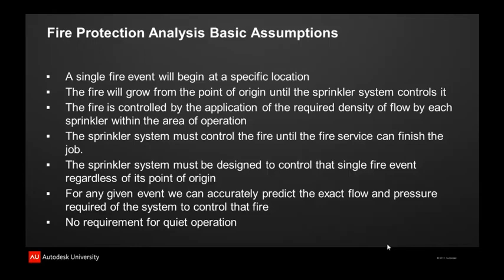Next, the sprinkler system must control the fire until the fire service can finish the job. So it doesn't have to operate all day long every day. It's just when there's a fire, and only until the fire department shows up and actually puts the fire out. This is pretty key, that our design basis or our assumption is that we're trying to control the fire. We're not really, generally, trying to put the fire out. Simply control it long enough for the fire department to show up.